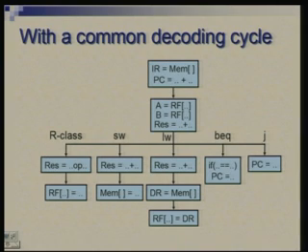Now the jump instruction has taken another hit here, and we are eventually using 3 cycles for it. But please remember that this is an instruction whose frequency of occurrence is comparatively much lower than others, and therefore, the overall impact of this loss in performance will be negligible.